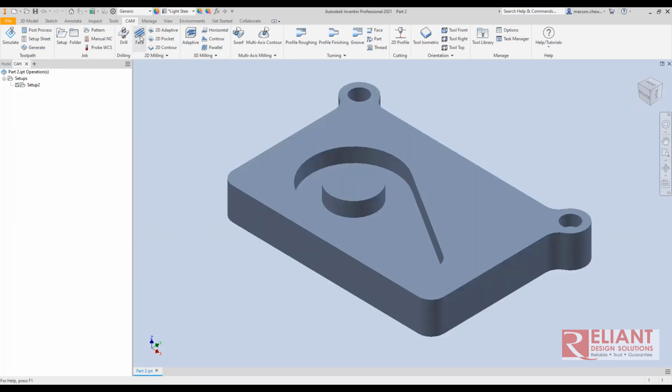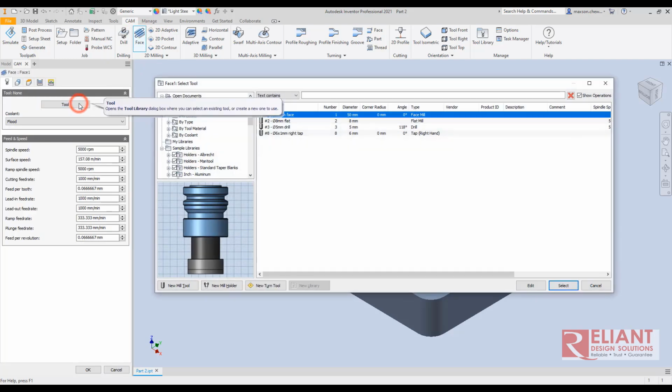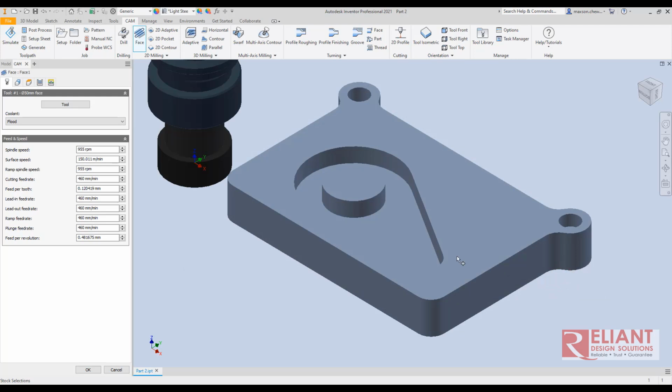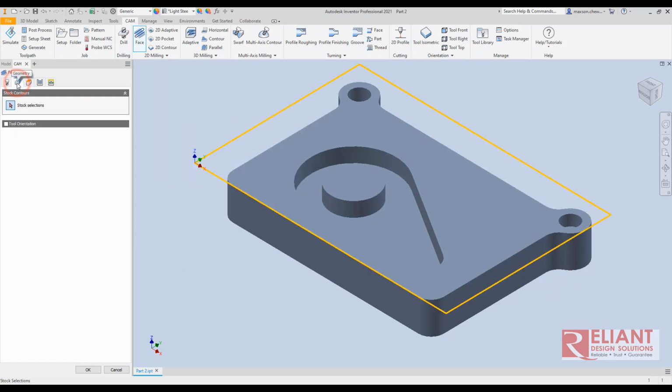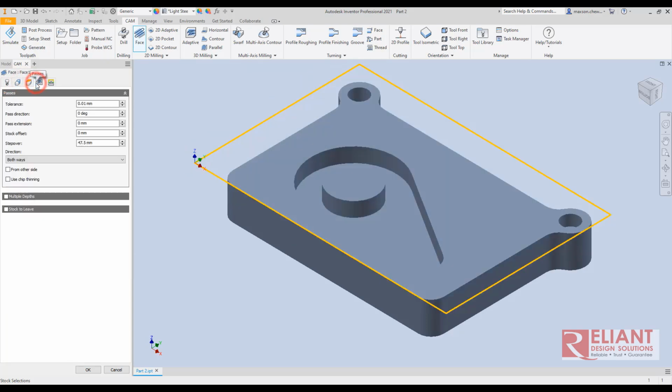now we are into stage 2, which is setting up the toolpaths. I'm going to use a face milling. So next we select the tool. There are libraries here. I'll just pick one. Then we select the geometry. Notice it's automatically selected, the geometry for facing.